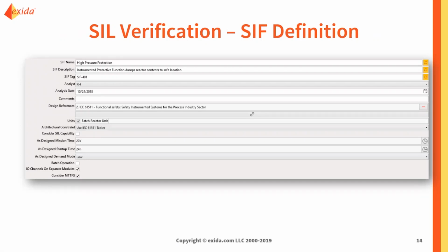Next, you can specify your as-designed mission time, your startup time, your demand mode. If you're doing batch operation, we can account for that. You can decide if you would like your I/O channels on separate modules within the logic solver for the SIF that you're modeling. And if you'd like to consider mean time to fail spurious in your